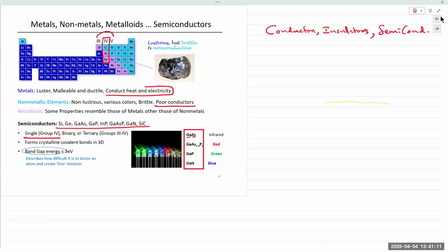When the light goes through the mask, it's blocked in certain areas, and where it's transparent, it goes through and exposes the photoresist. Then we take our silicon wafers and stick them in wet chemical, which washes it away. We wash it with water, we dry it with nitrogen, and the pattern is transferred onto the wafer.